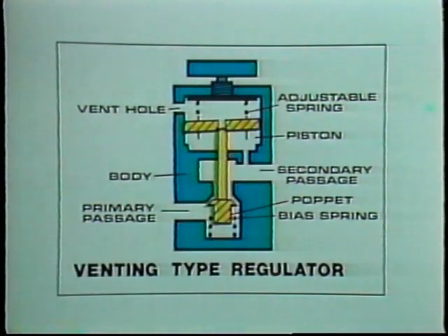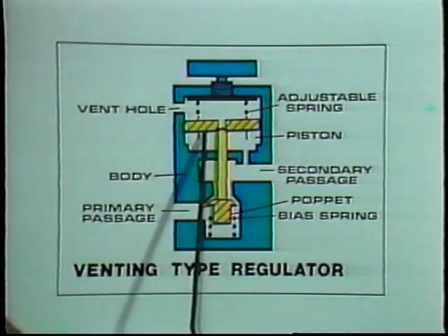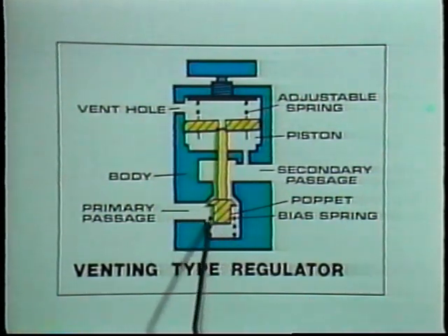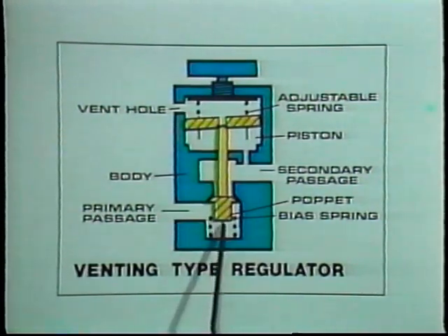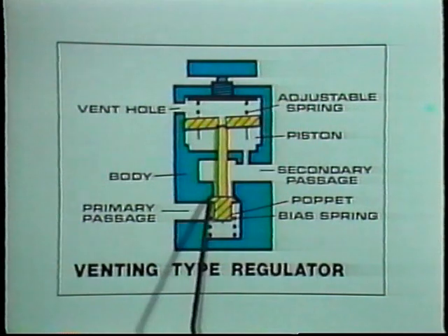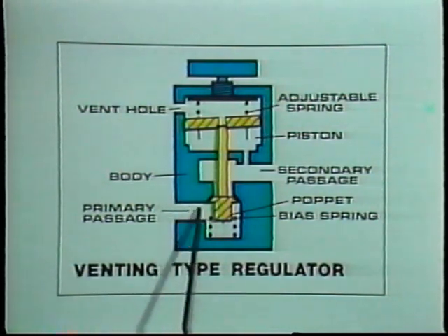Okay, so what happens if the secondary pressure goes up to a pressure higher than the valve setting? As we've said, this might be caused by a thermal expansion of air or a big external load pushing against a cylinder piston. Well, the extreme secondary pressure would continue to push the piston in an upward direction. Because of the spring, the rod and poppet follow it upward. But look what happens to the poppet. It seats, fully shutting off air from the supply, so pressure cannot continue to build from the inlet.